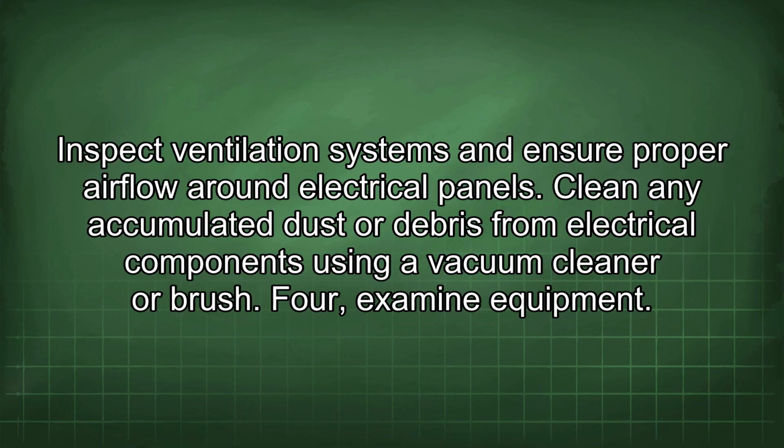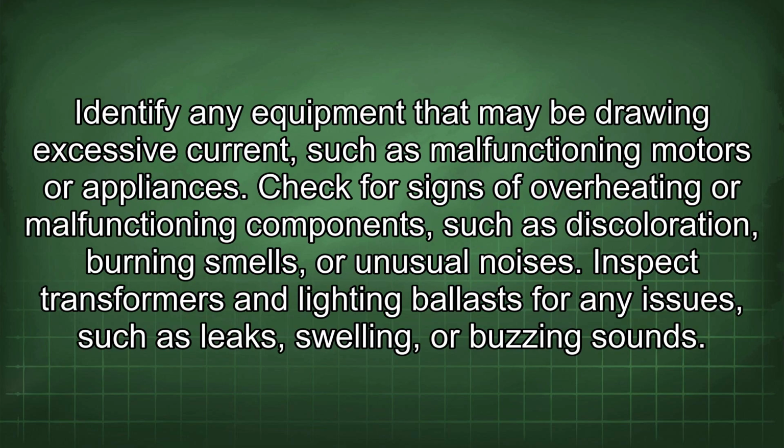4. Examine equipment. Identify any equipment that may be drawing excessive current, such as malfunctioning motors or appliances. Check for signs of overheating or malfunctioning components, such as discoloration, burning smells, or unusual noises. Inspect transformers and lighting ballasts for any issues such as leaks, swelling, or buzzing sounds.